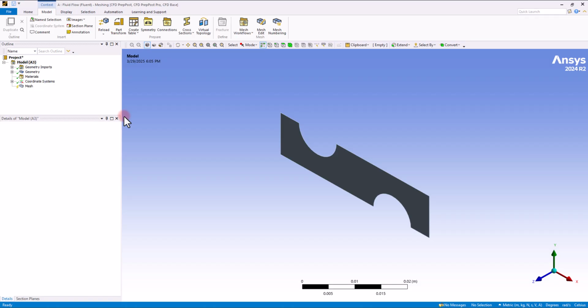All right, in ANSYS Meshing, we've got 2 main missions. Our first and most important mission is dividing a computational zone into different computational cells. And then in the second mission, we have to specify and name all of our boundaries. So let's begin with our first mission.